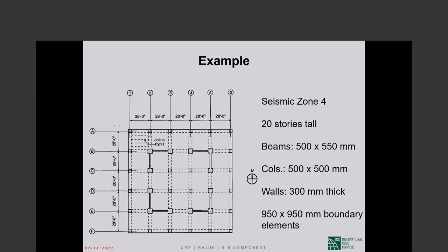Or you can try to provide ductility. Obviously, you will not comply with the special moment frame requirements, but you can do that by wrapping from the outside. There are techniques, or you can do jacketing. You can build columns around the existing column in which you have ductile detailing built in. So there are ways of approaching it.